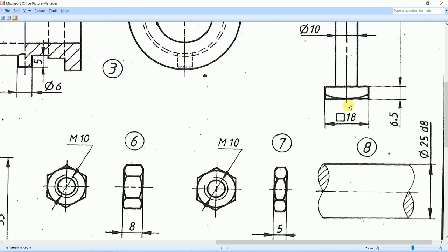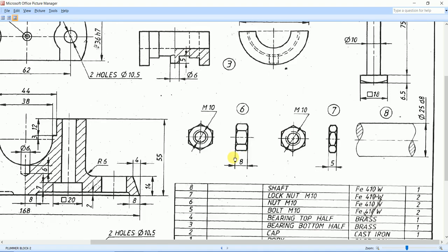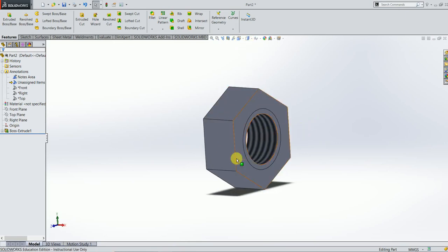Now, similar to how I demonstrated the chamfering of the square-headed bolt, in the same way we can go for chamfering the hexagonal nut. So let me show that. Let me demonstrate now how the chamfer can be added. If you feel that this much is sufficient for the assembling, you can treat this itself as the final nut and go for assembling. Otherwise, if you still want to accurately get the nut, go for adding the chamfer. So now I will show how to add the 30-degree chamfer for the right face and left face of the nut.